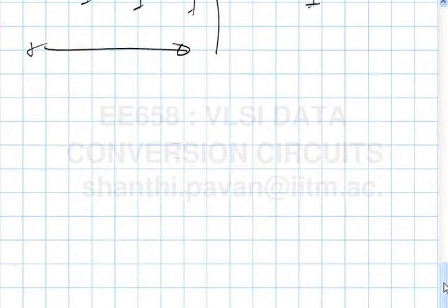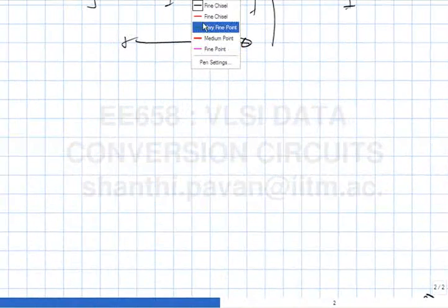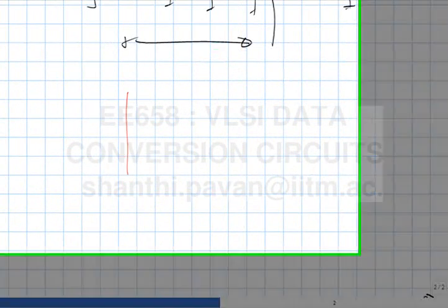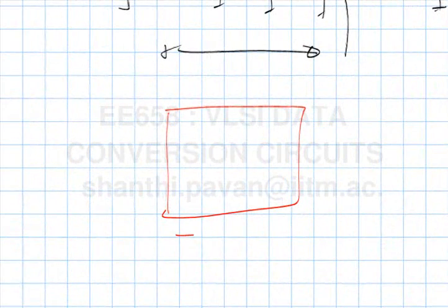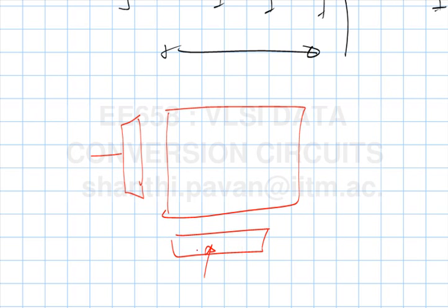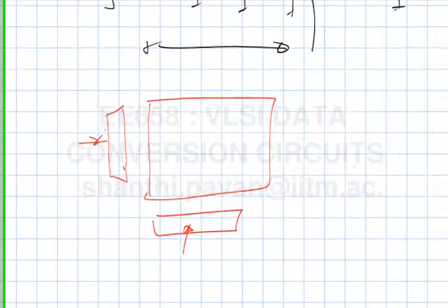The DAC current sources are now sitting in a nice clean square array. So you have the row-column decoding logic, and when you have a segmented DAC, the thermometer DAC is basically realized like this. The binary section is anyway small, so you can either do that also this way, or you just put them in a straight line. Okay, and so this is how it happens. Now